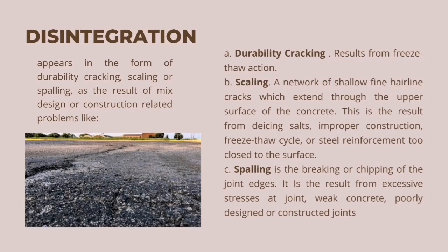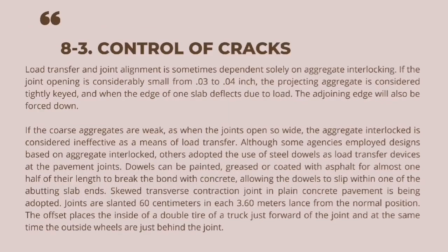This is the result from deicing salts, improper construction, freeze-thaw cycle, or steel reinforcement too close to the surface. C. Spalling. It is the breaking or chipping of the joint edges. It is the result from excessive stresses at joint, weak concrete, poorly designed or constructed joints.